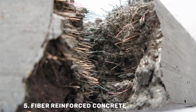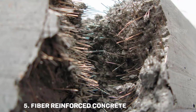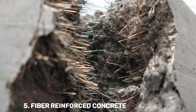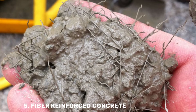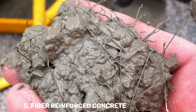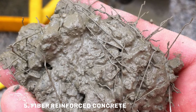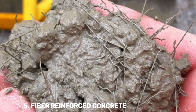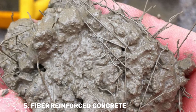Next, fiber reinforced concrete. It is a type of concrete in which steel fibers of 10 to 20 microns in diameter and 10 to 50 mm in length are used. Fiber increases resilience, tensile strength, flexibility, and other qualities. The fibers may be of different materials like steel, polymer, glass, carbon, or even natural fibers like coconut fiber, etc. These are used in places where increased resistance to cracking is required.